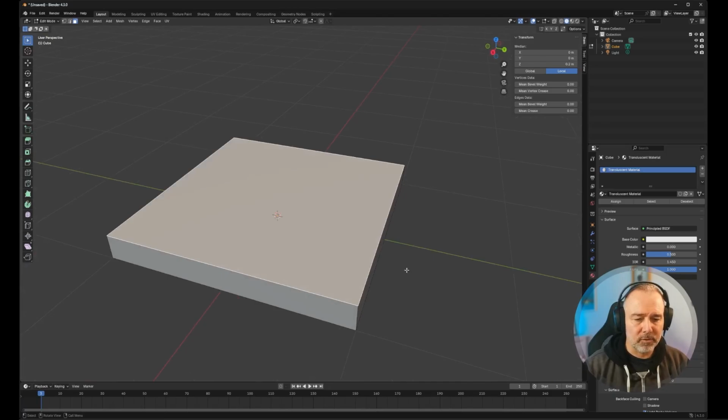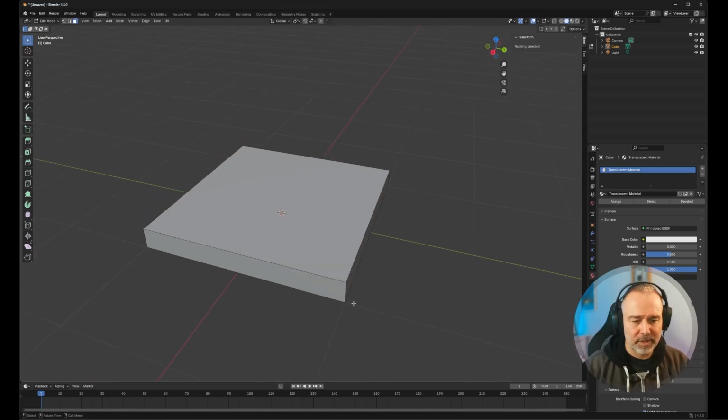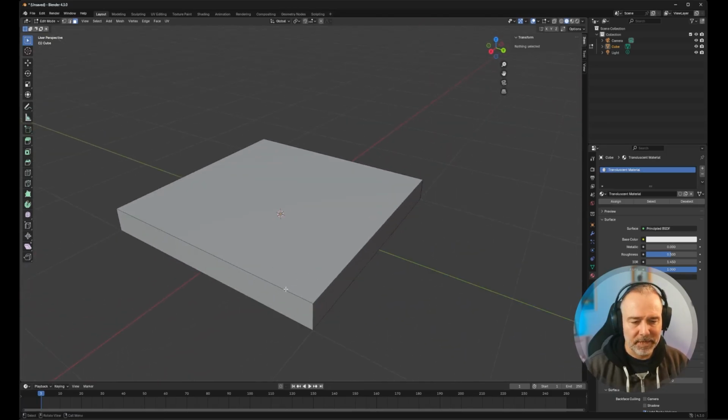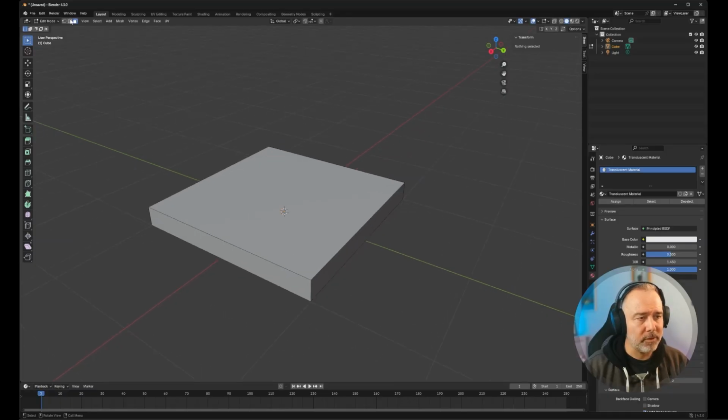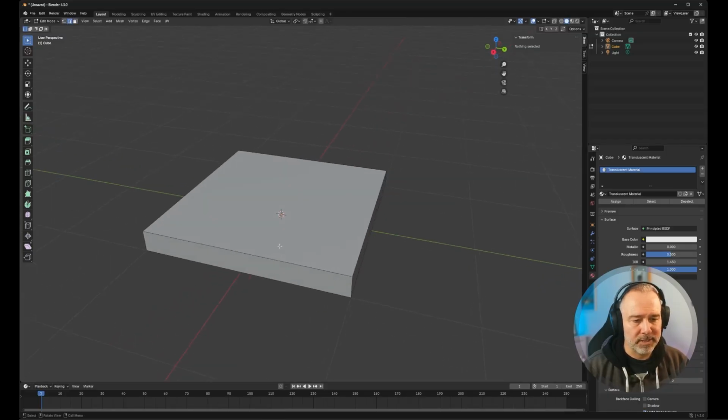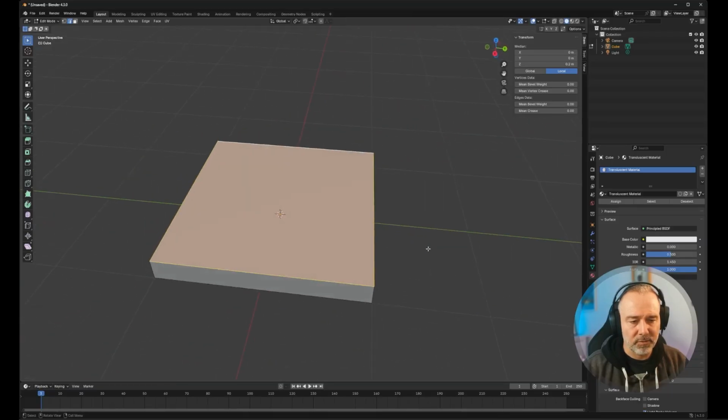What I want, in order to break a bit that computer geometric aspect, is to add what we call the bevel here. To do that, I'm going to go to edge mode and press A to select all the edges. It looks like it's the faces, but it's because if I select 2, 3, 4, like that, it showcases the full face.